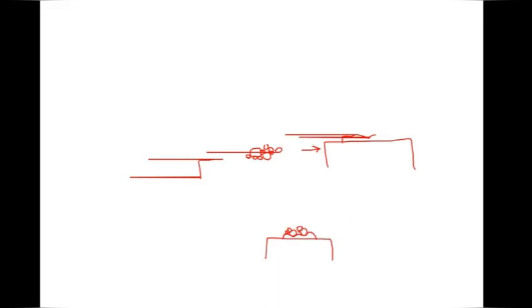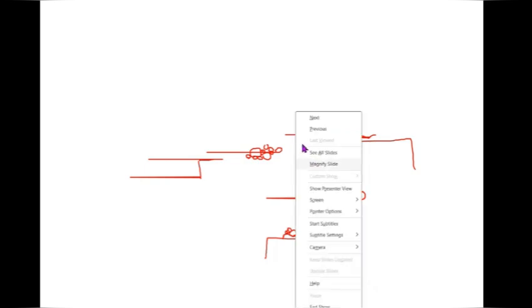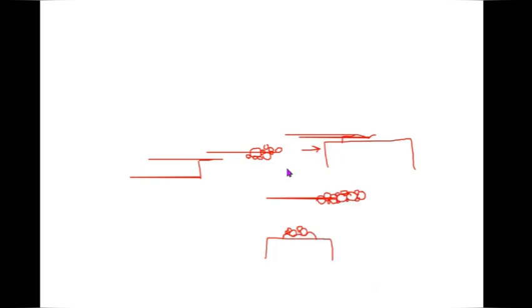I hope it's clear. If you choose only one powder size, then there will be voids in between. But if you have a distribution, then you can fill the voids with the smaller size powder particles. That's how you choose the size distribution instead of one particle size, so that you can fill the void and there will be less porosity in the deposition, because there will be less space available in between the powder particles. So that is the concept.